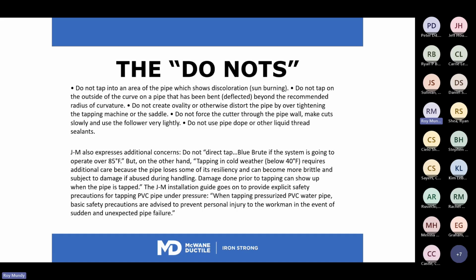This is language actually out of the JM Eagle PVC brochure and manual. Even though they contend that, hey, you can tap PVC pipe directly just like you can ductile iron pipe, here are the things you do not want to do. You don't want to do that when you're in cold weather. You don't want to do that when you're in hot weather. You definitely don't want to do that if there is a bend in the pipe, as I just mentioned.